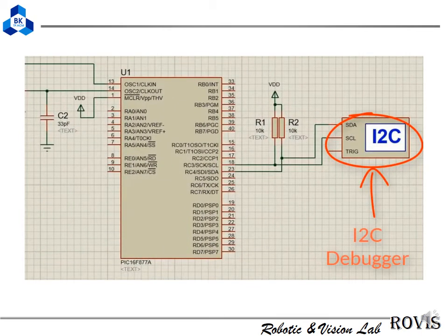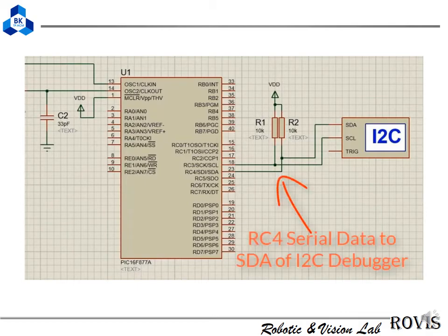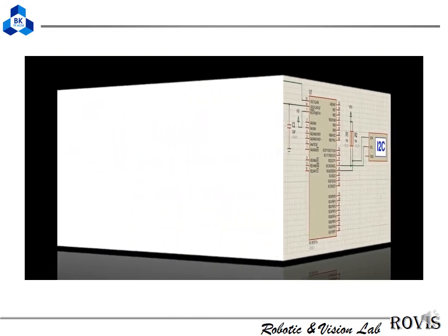Then we have the I2C debugger for our debugging purpose. We have connected RC3 serial clock to I2C debugger and also SDA RC4 serial data.